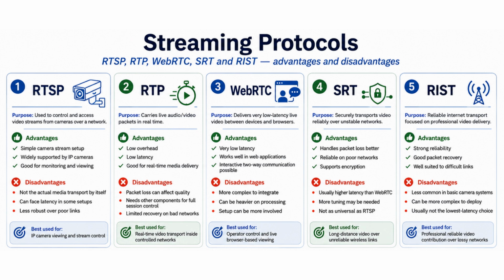WebRTC is designed for extremely low latency, interactive video. It is useful when a vehicle operator needs near real-time video through a browser or control application. SRT and RIST focus more on reliable video delivery across unstable or lossy networks. They can recover missing packets, but this additional recovery may increase latency.